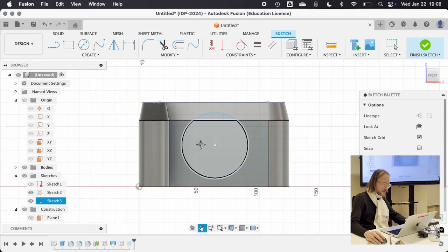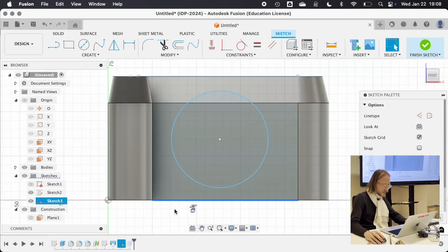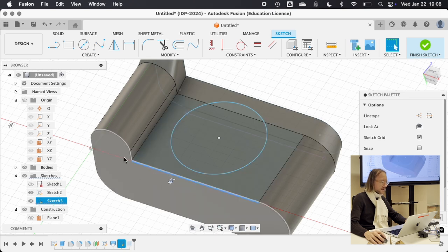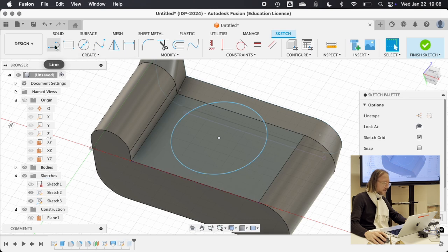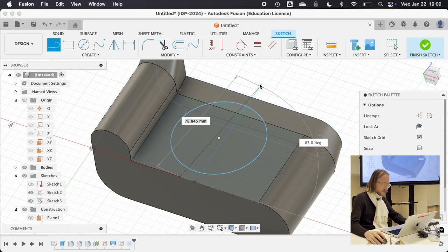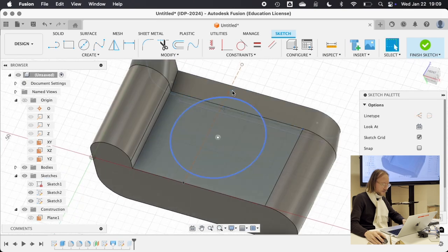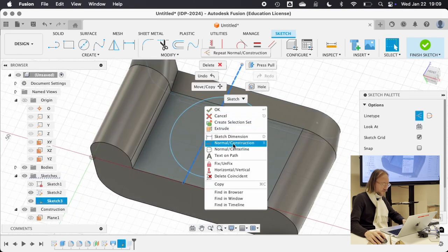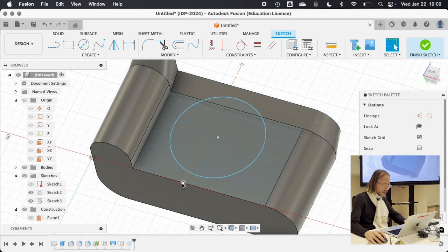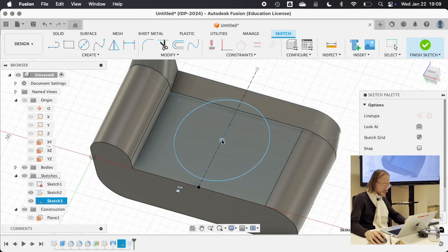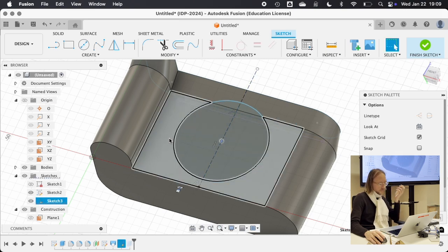It depends on what you're centering to. You can use any geometry that exists for reference. So in this case, I have this line. What I can do is create a line that's connected to here and then goes up vertically, and I can make this a construction line. Then I can select this line and this point and make it midpoint. And now I can align this to this. So now they're centered. That's one way of doing it.